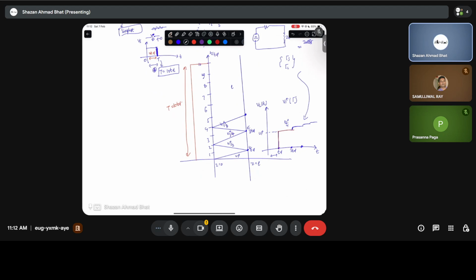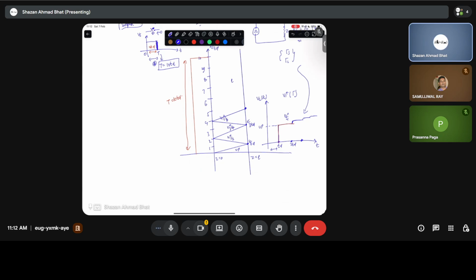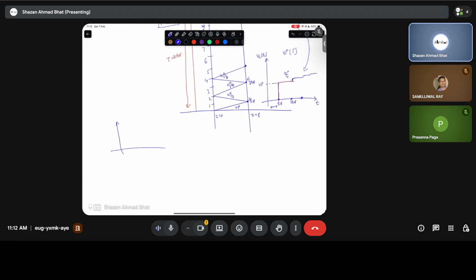And now, what's going to happen? This is basically going to happen because you were giving a voltage like this, which was 10 times TD, a step voltage. This is a function of t. At the load end, what you will basically see is something like this. It will go on increasing and then it will go on reducing, and this will be around 20 TD. So this is the function of time towards the load end.